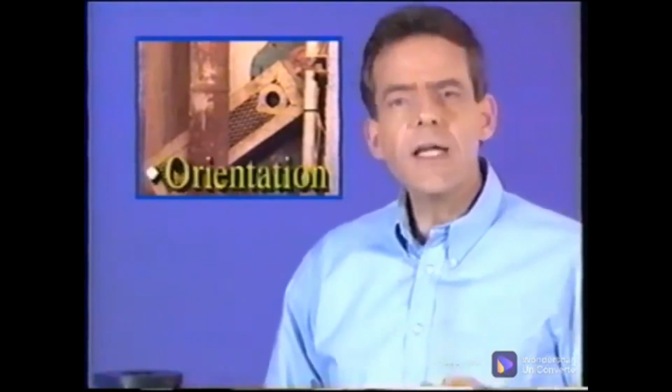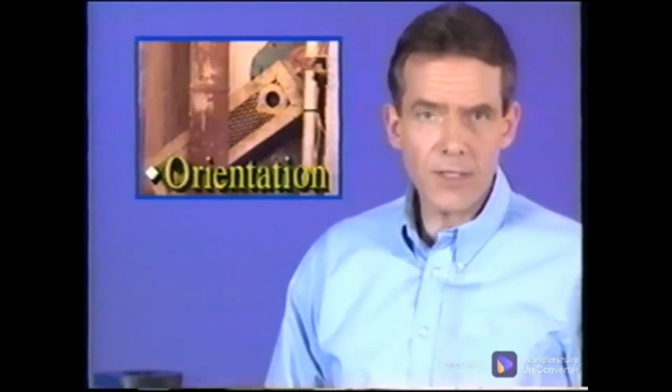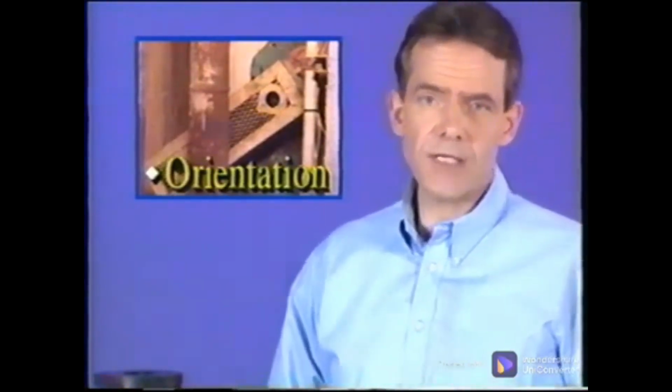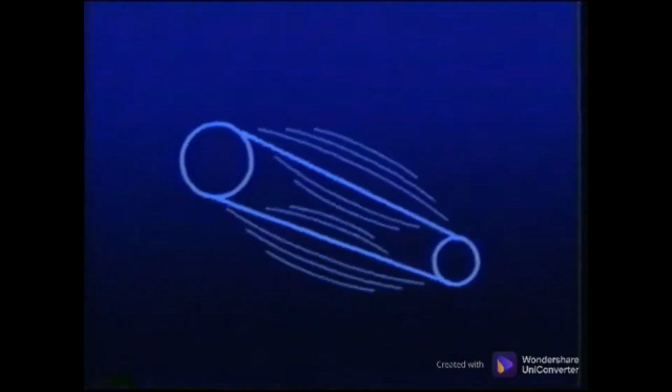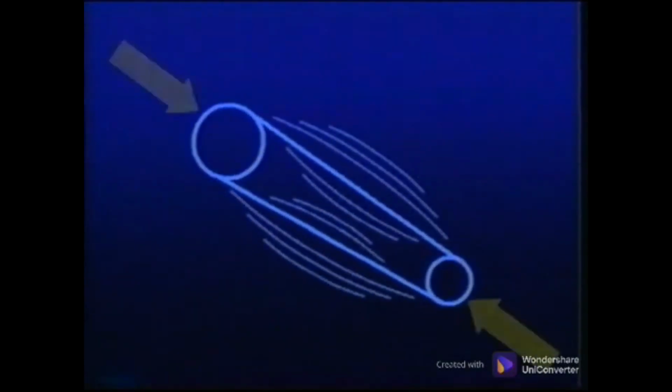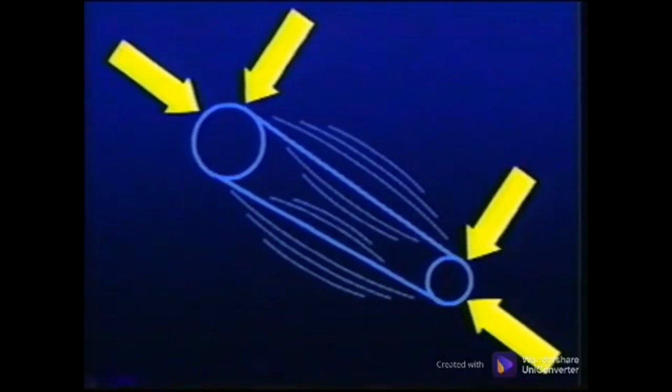Belt-driven equipment has special considerations for selecting the measurement locations. Although the common rule of 2 radial readings and 1 axial per shaft still applies, it is the orientation of the radial readings that varies depending on machine design. When the center lines of the motor and driven equipment are in the same horizontal plane, there is no change in the measurement locations. When the shaft center lines are not in the same horizontal plane, 1 radial measurement should be made in line with the centers of both shafts, and the other should be 90 degrees to it.